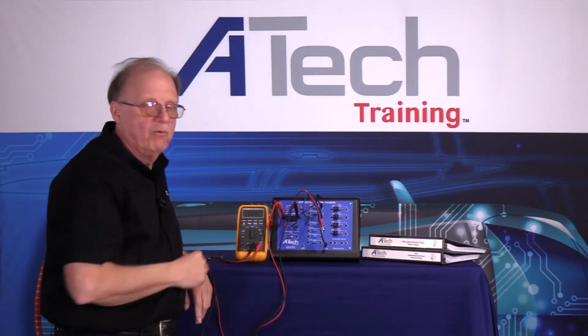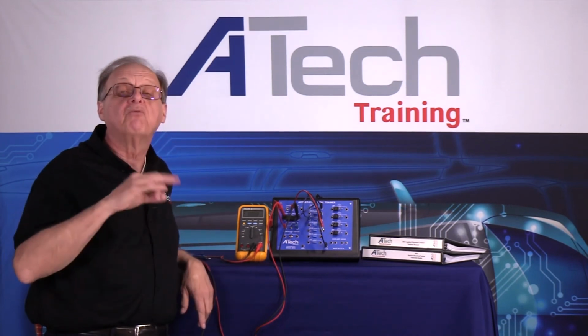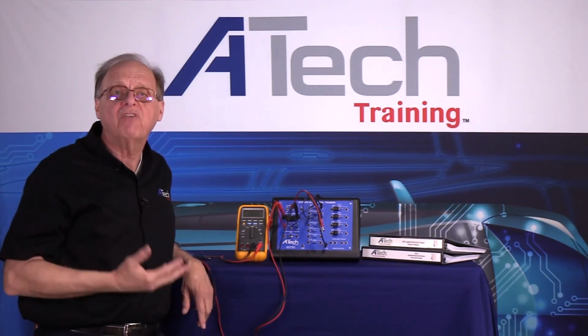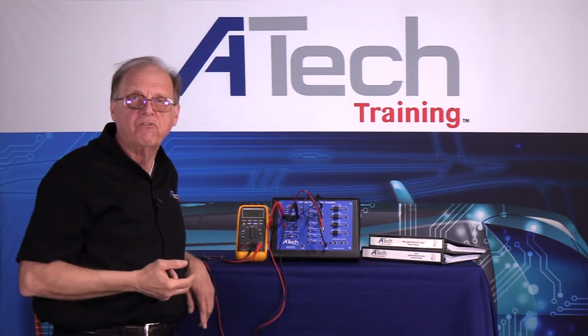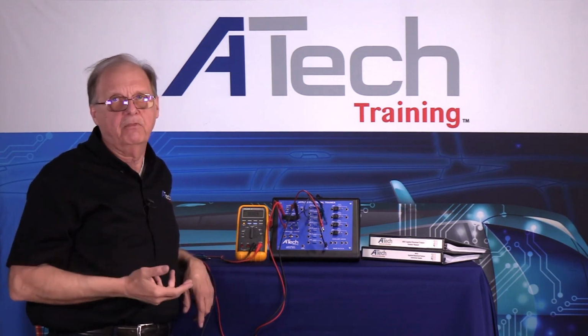I could check my switch. If there is an established voltage or established resistance reading, that's a great idea. If you have no established reading for resistance, you need to use the voltage drop method.